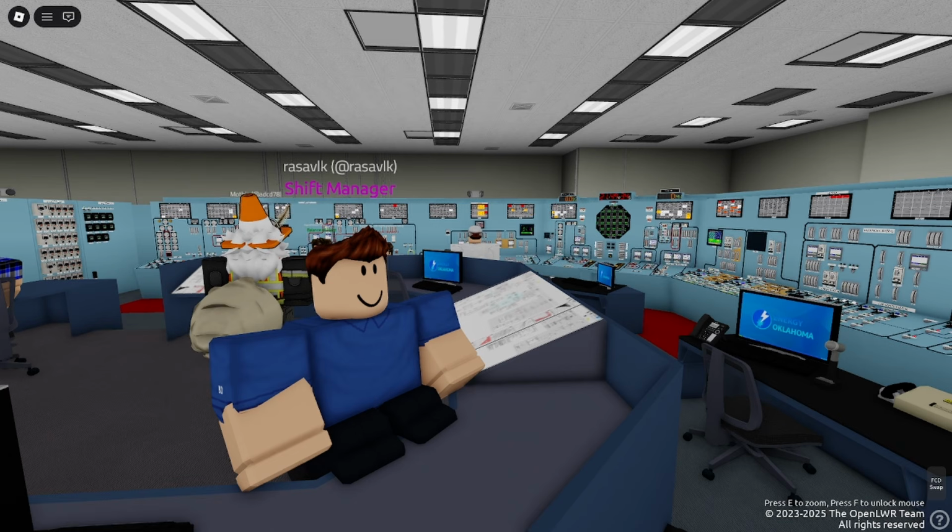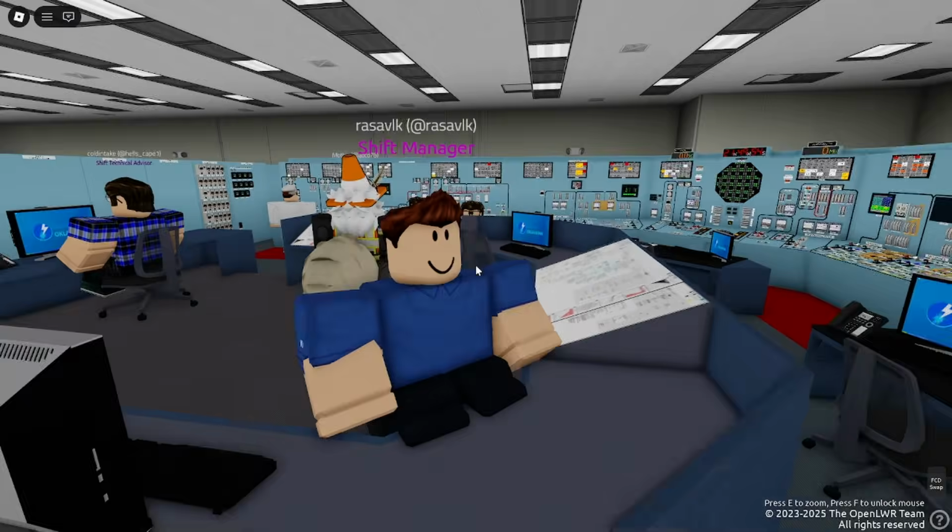Yes. I would like you to further depressurize the RPV down to 300 using SRVs at a rate of 50 psig per minute. I understand you want me to decrease RPV pressure to 300 pounds using SRVs and not exceed 50 pounds per minute. That is correct.